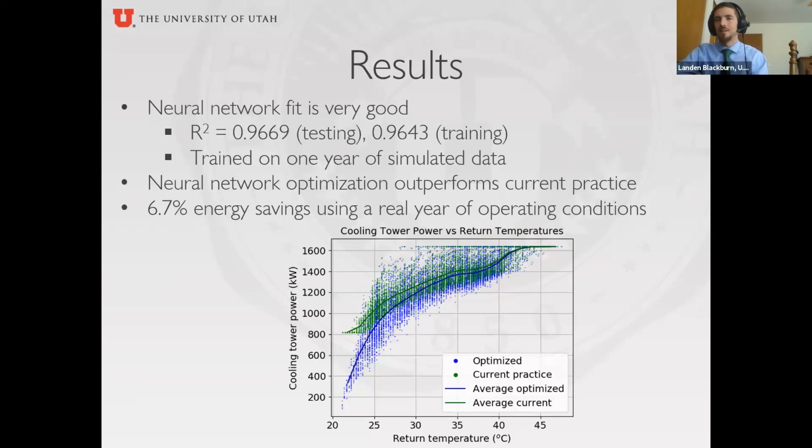The main thing we're taking advantage of here is the room to adjust the relative speeds of these fans. And as you approach maximum capacity, you end up with all the fans at or near 100%, so you don't really have any room to move them around. The optimizer can't really do much, so you end up with the same performance that way.